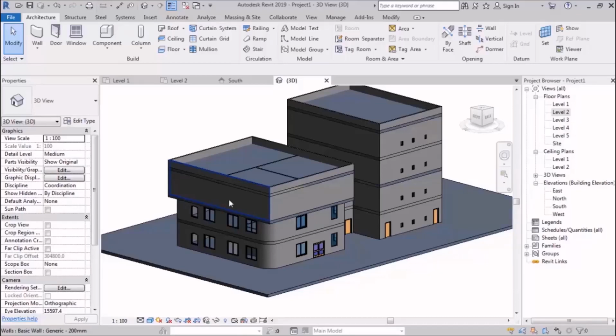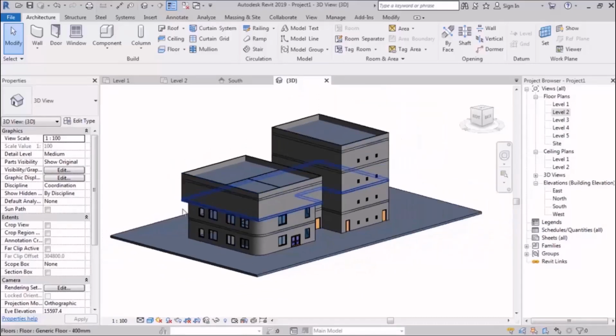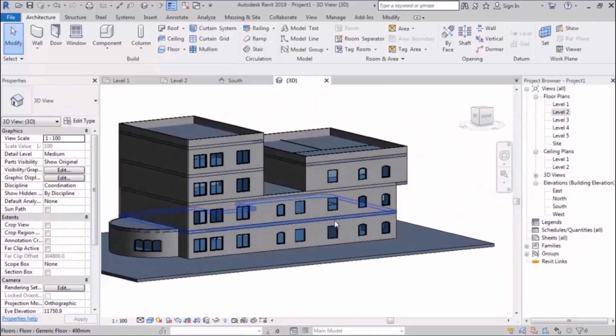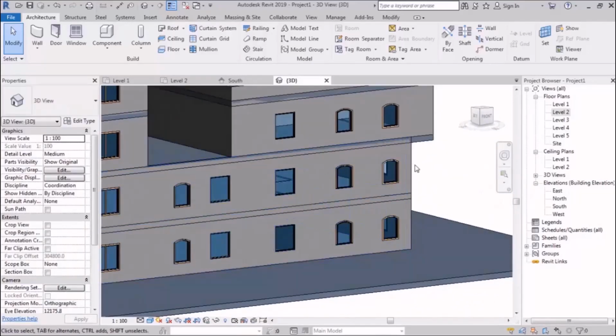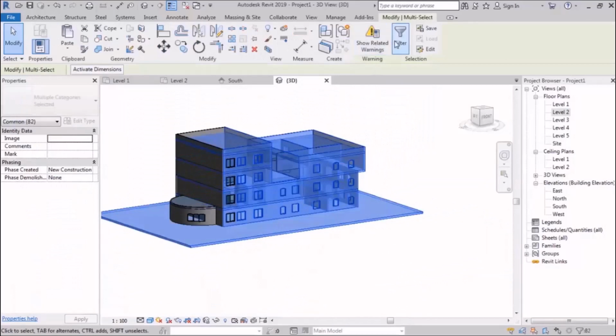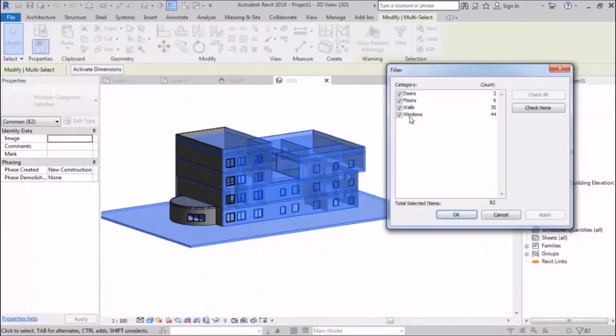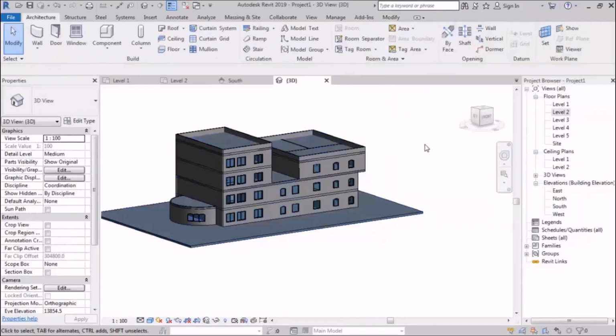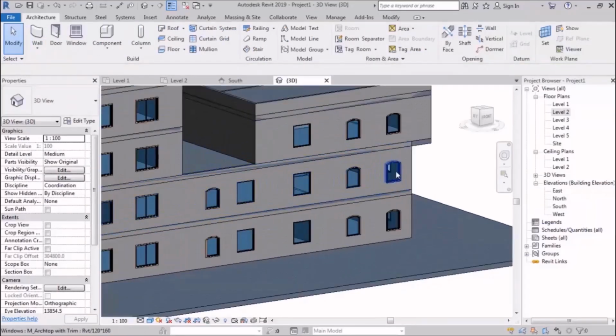Alright, now a question. If I suddenly find out that all these windows that have an arc at the top of them are not good, they don't seem good to me, and I want to select all of them and turn them into another window, so what should I do? You might think of that filter again, but it's wrong, because the filter does not understand the different kinds, but the different objects, alright? So we need to use another technique.